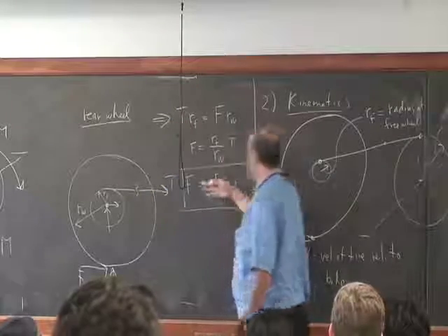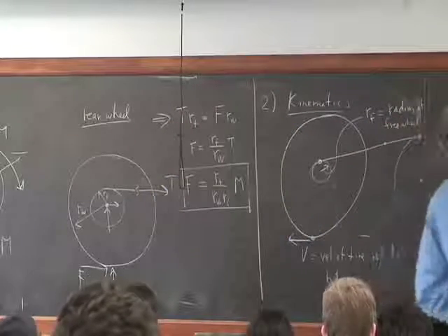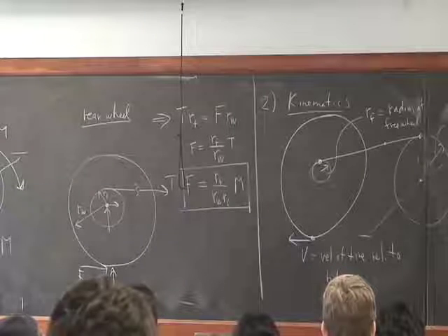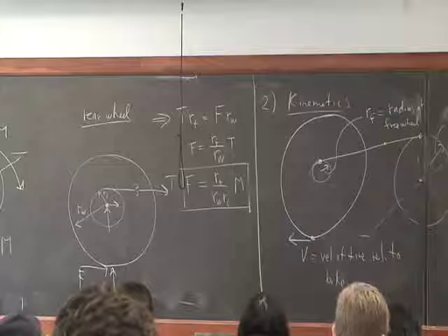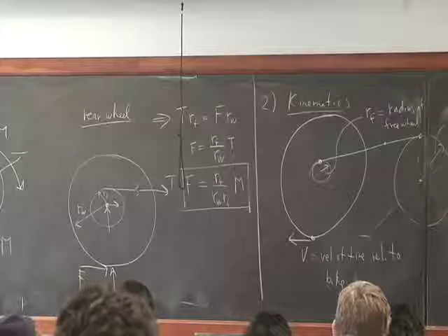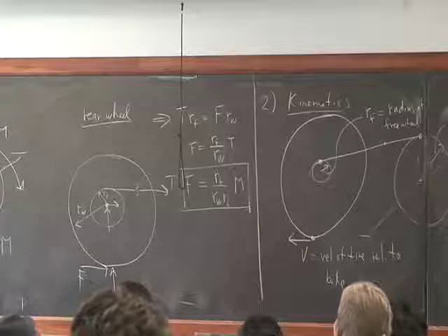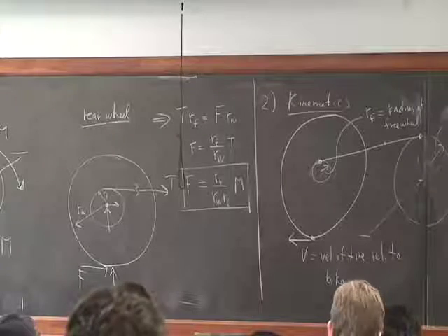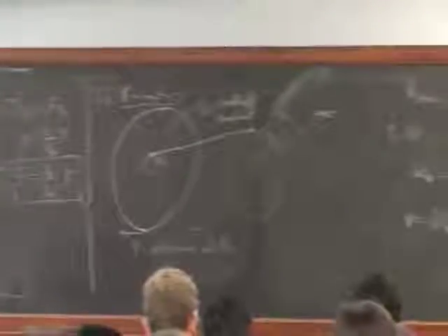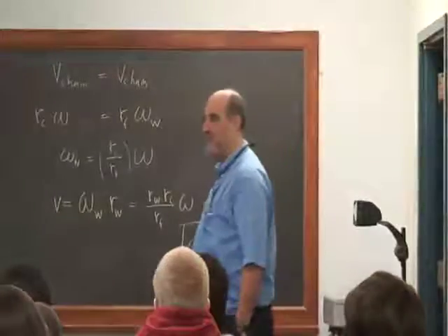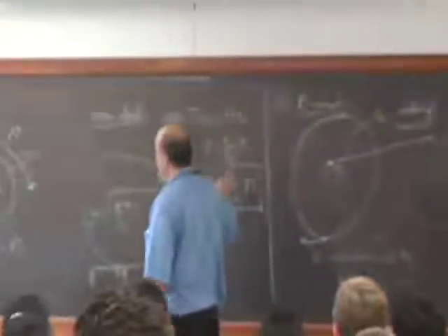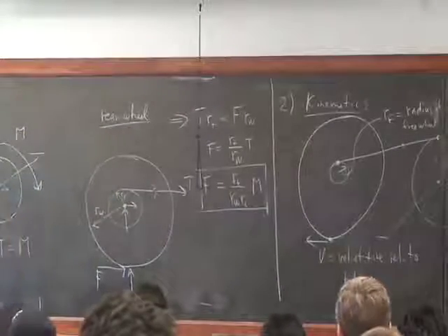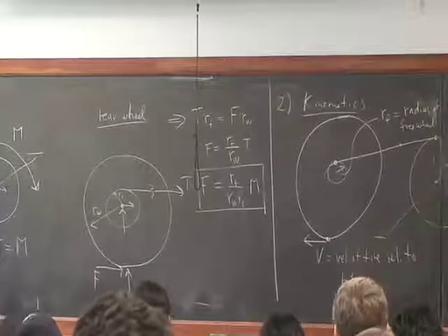So you see that the ratio of the force to the moment is equal to the ratio of the two angular velocities, only reciprocal, just like on the teeter-totter. Why do they have to be reciprocal? Because power has to be balanced. Where there's a bigger force, there has to be a smaller motion for it to balance the other side. Which is why you can take any two of these equations, 1, 2, and 3, and derive the third.